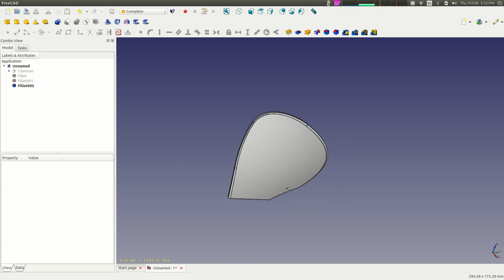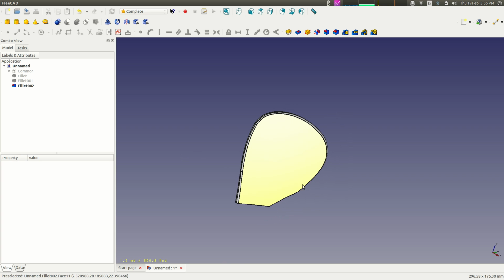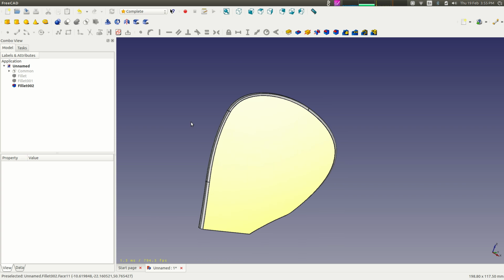Now I'm going to do a little bit of an assembly. It's not quite normally what you would do with SolidWorks or something like that. FreeCAD has very limited assembly tools, so I think all you can really do is just put things on an axle, so not extremely handy. In SolidWorks you can actually constrain faces and make coincidences of circles and cylinders and stuff like that, so you can really assemble stuff really quickly. With FreeCAD it can be a little more difficult. Sometimes I find myself just moving stuff, dimension by dimension, just adjusting XY coordinates and then rotating things. So that's essentially what we're going to do.